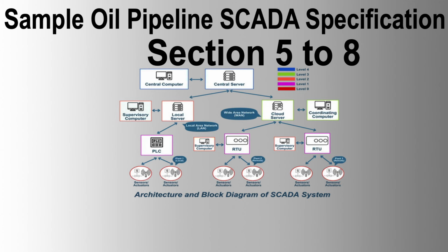5.8 Labeling. All enclosures and equipment within shall have identification as per the owner's philosophy. 5.9 Terminations and Input-Output Wiring. RTU configuration includes provisions for terminating all field multicore cables, including spares, terminating all system cables, including spares and interconnections, intrinsically safe and non-intrinsically safe digital and analog signals.